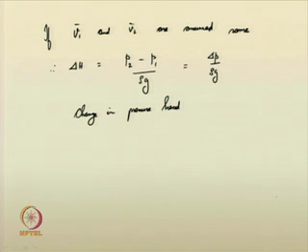So, that way it is now easily understandable that even though you supply energy head, and the total energy consists of pressure head, velocity head and datum head, the changes in velocity head and datum head are negligible, and we consider the entire change in the energy head is reflected in the change in the pressure head of the system.